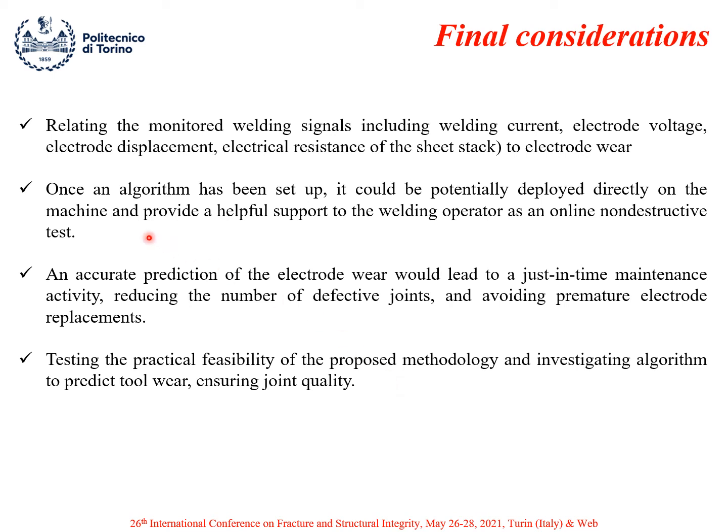The aim is to define an algorithm that allows to consider directly which is the electrode wear directly on the machine, in a way that the welding operator is able to identify if a joint is sound or not only by analyzing this welding data, employing them as an online non-destructive test.